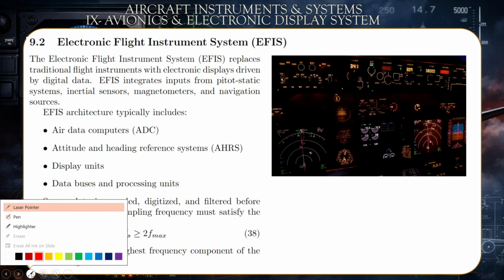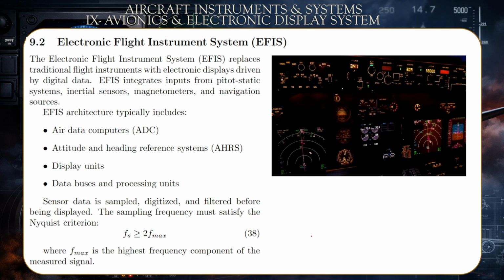Now, this is how it works, because it might have seemed ambiguous. Say you have a measurement of the temperature from the EGT. This is the signal being collected from the EGT. In order to convert it into a digital value, I need to take samples, because you cannot digitize an analog signal, which has an infinity of values. So I need to break it down into samples.